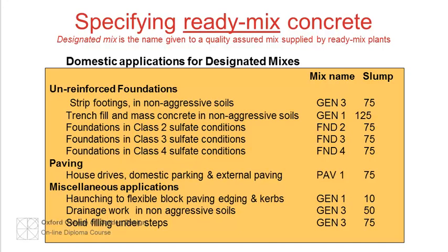Ordering ready-mix is relatively easy. Put simply, you say what you want it for, the supplier does the rest. The term designated mixes is the name given to the quality-assured mixes supplied by ready-mix plants. The table on the screen gives the typical uses and the appropriate reference codes.